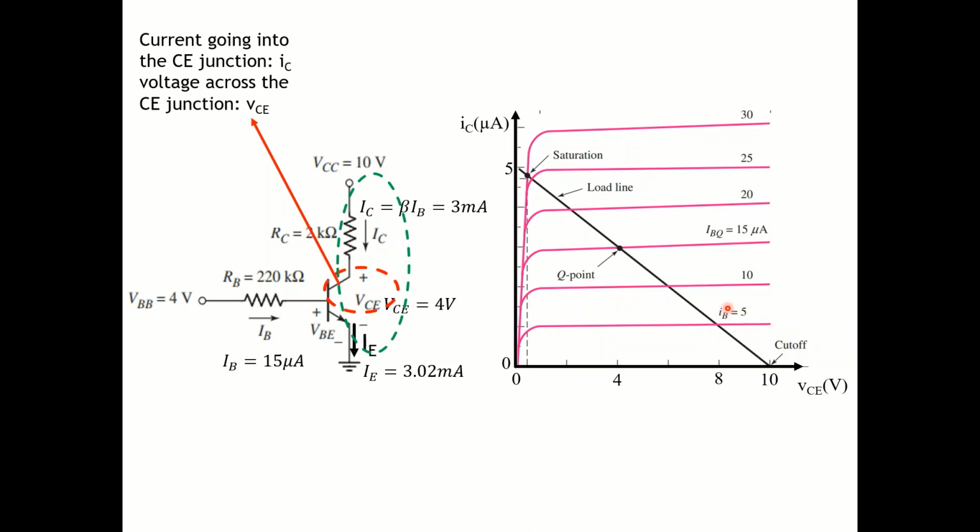And you all know that the relationship between collector current, which is the value of this pink line right here, is linear to the base current. Collector current is linear to base current because IC equals beta IB. But there's a catch, and let's talk about it later.